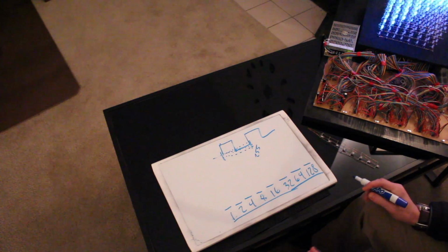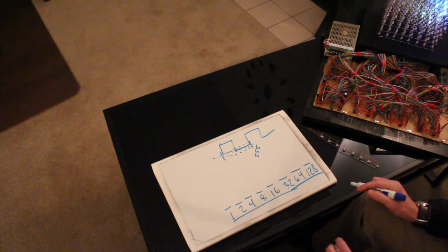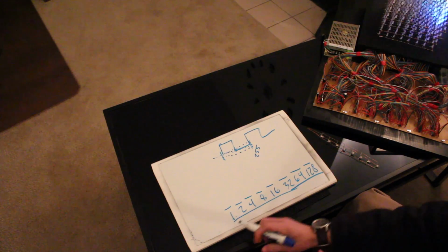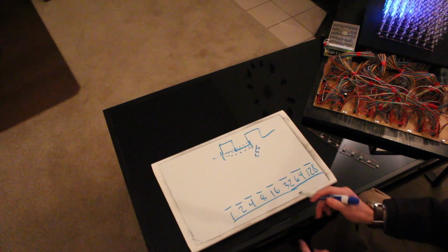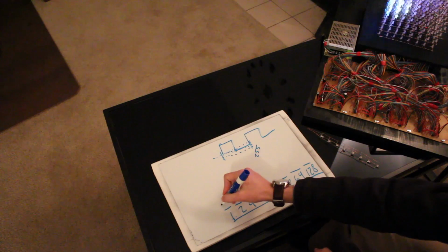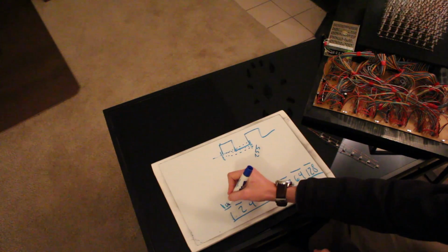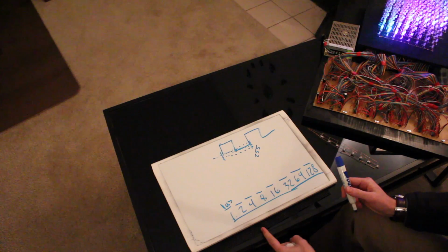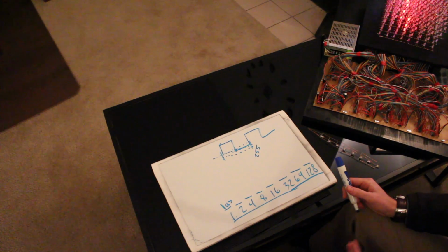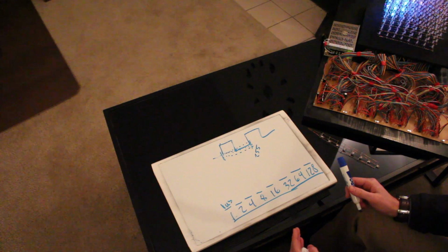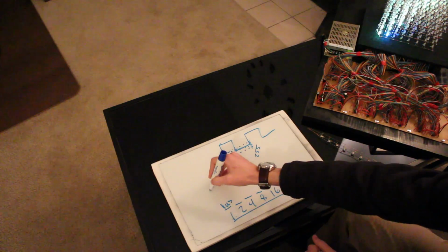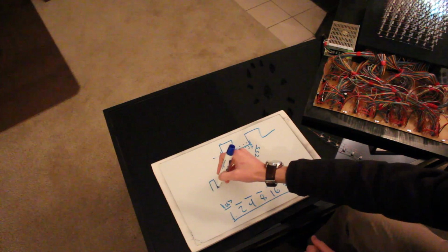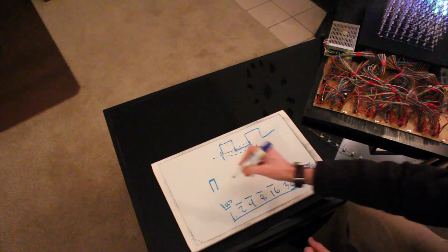But what you do with bit angle modulation is you give each value a time. Let's say 1 is equal to 1 microsecond. So if I'm using bit angle modulation and I wrote a 1 to the value that I'm writing, it would only be on for 1 microsecond.